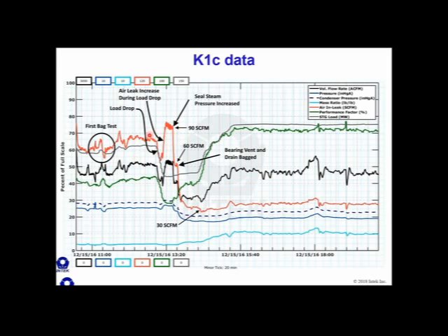There were 2 leaks associated with this one leak. As we went along, we repaired the leaks. The total air in-leakage came down. The water to air mass ratio goes up above 1. So it's better now, but they still can reduce air in-leakage further to reduce their condenser pressure.